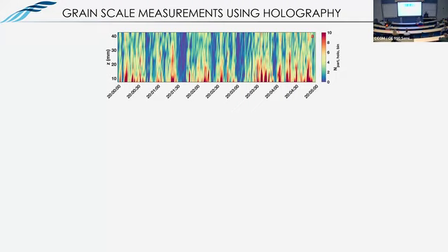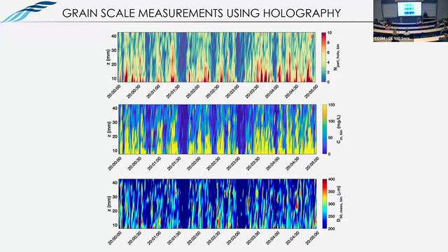It shows that close to the bed, there are more sand particles than even 4 or 5 centimeters above. Once again, not surprising, but we're measuring things at really high resolution. And because we know the size of those particles, we can actually get concentrations directly, which is often pretty hard to do. As I said, we can do image analysis on the particles themselves, so we actually know the size of every grain that's moving through.